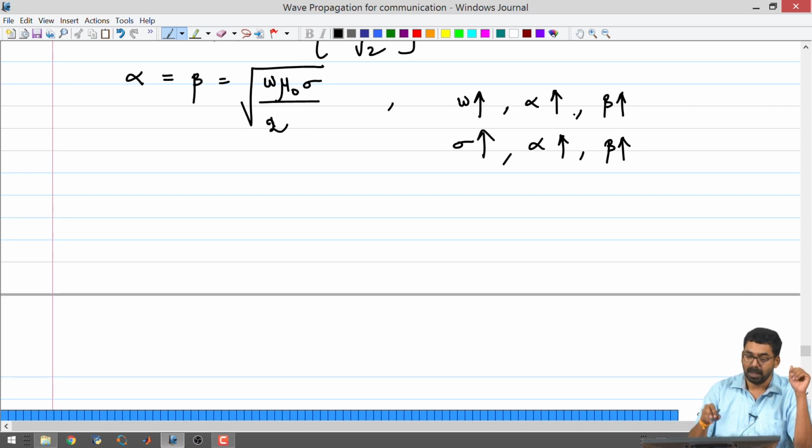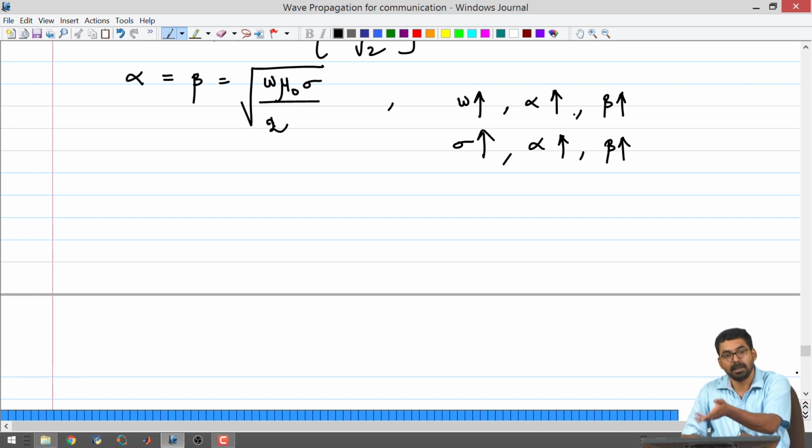But then later on we have switched to much higher frequencies. But the challenge is, as the frequency increases, the range of your system for communication will naturally decrease because of attenuation. Even in the air you will have some content of, say, water vapor, etc. These will also have tiny amounts of salts and other things, which will increase the conductivity, and then as high frequencies happen you will end up with alpha becoming higher.